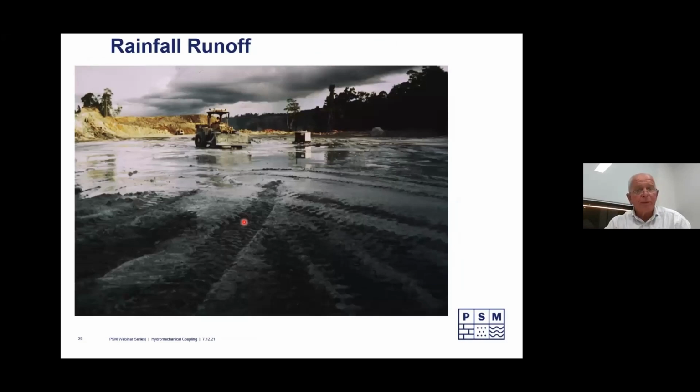Sometimes we create problems for ourselves. A big flat area, no drainage, there's clouds there and it's raining all the time. Again, we're going to get transient pore pressures developed as a result of this that are eventually going to make their way to the deeper groundwater table.